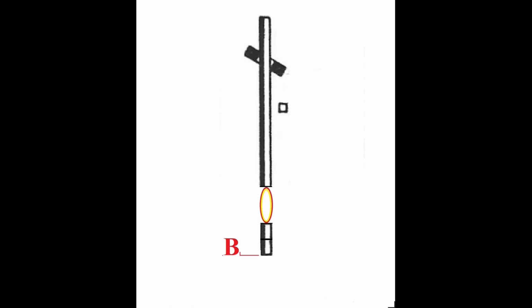The voltage across the arc gap has increased and, as described previously, causes the upper electrode to move down to close the gap at C. The top of the upper electrode at C has moved down as well because it has been shortened as a result of the consumption of its carbon in the arc. The process begins again at D. More carbon is consumed and the arc has lengthened to the point where control action is again initiated.